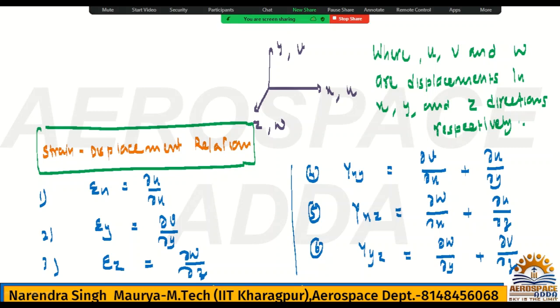All right, first you need to remember, this is very important. Now in my previous lecture I had also discussed the relationship between stress and strain. This relation is called the strain displacement relation. How many strain displacement relations do we have? Total 6. How many displacements do we have? Only 3. U, V, W are the displacements, so 3 displacements, and how many strains? 6. Please remember, this is very important, they have asked it in examination.